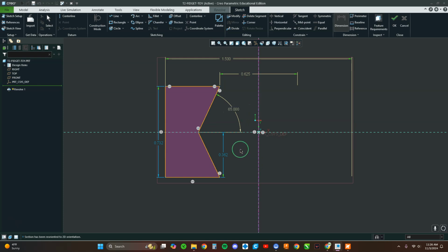And the reason we're putting in 65, if you're wondering, for those of you that want to learn a little bit about 3D printing, is that there's certain angles where, if you think about this piece, when it starts building it, it's going to be okay overhanging the base plate. Obviously, a 90-degree angle is fine, it's just printing straight up. But as this angle gets smaller, it's harder and harder for that print to print over a little bit more, a little bit more, a little bit more. 65 is a nice round number. It'll also keep our center piece inside there. That works well for this.